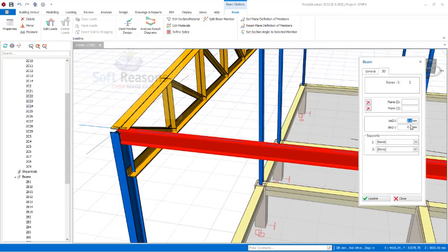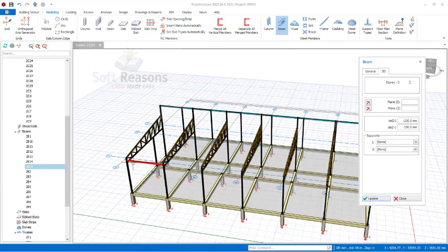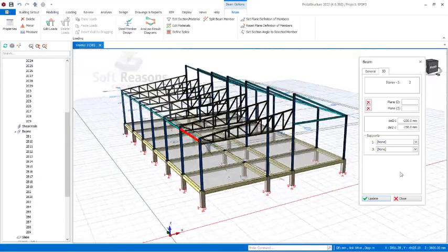Let's say we send it down at 250 in that top side. For the J side we send it also 250 downward. You have to prefix it with minus. Click on the update to have it like this. So this is what we are going to have throughout these provisions. Click right there, yes option, to have that placed successfully. Click on the close options.